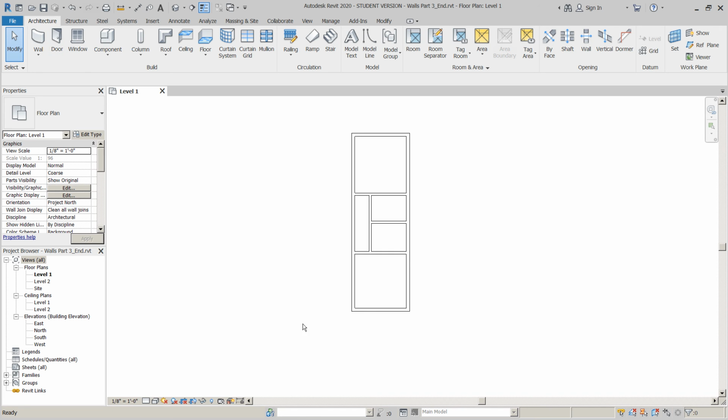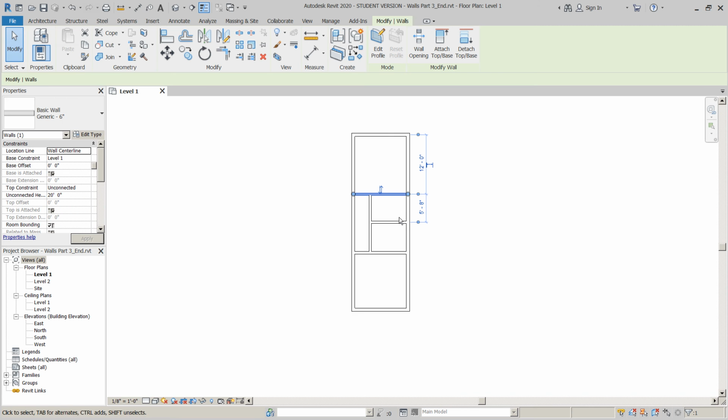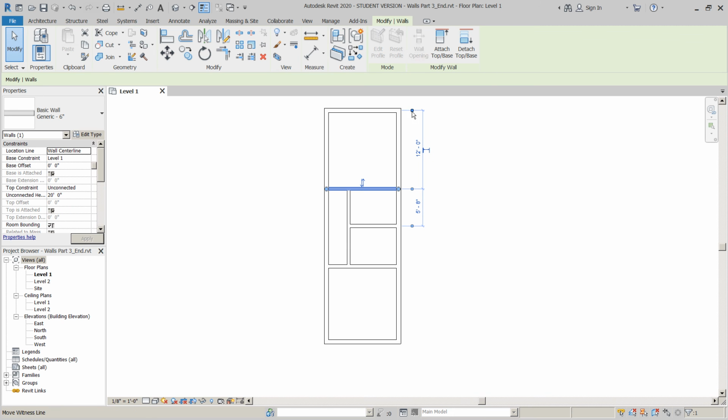So now we're going to go back and refine some of the dimensions for the spaces that we've created here. So I'm going to click on this wall, and I wanted you to note here the dimension that we have. This is called a temporary dimension, and it looks like I've placed it very well, I wanted exactly this dimension. Let's check here the lower one.